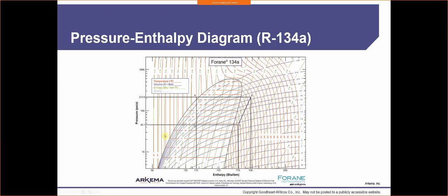So if I were to compare this chart to an R22 or even a 410A, they're all going to have different temperature glides, which are going to affect how the refrigerant is going to act and how much cooling we're really going to get out of a space. All right, it's the simplest, easiest way for me to explain it.